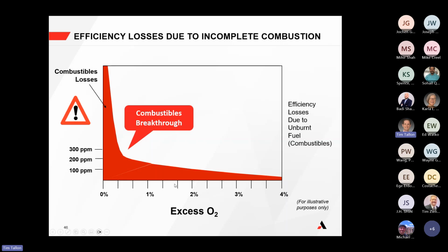Now, again, this is for illustrative purposes, but before you get to stoichiometric conditions, before you get to perfect air-to-fuel mixing, you actually see this before that. So how do we monitor for that? It's important to have a combustible measurement to monitor for that.